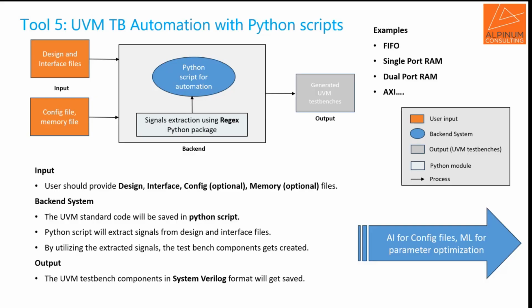So as a whole in the picture, this UVM test bench generator is going to generate the test bench, which will generate all the test bench related files and the tests and the sequences. But with integration of this AI model and the flow, it will guide the stimulus based on how we want to get our goal, score the coverage quickly, and so on.